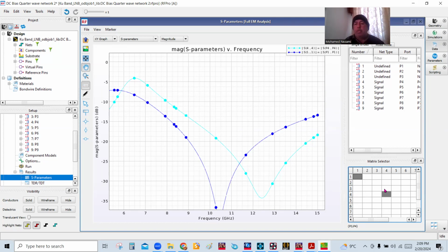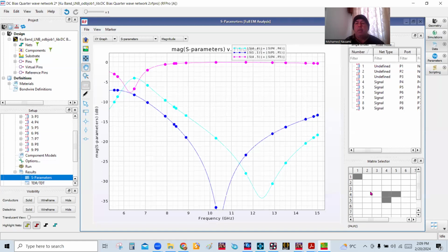And so if you go from 3 to 4, I mean from 1, 2, 3, 4 to 5, you can see that it's minimal loss as well, okay? Where if you go from 1 to 2, it's the same thing. So basically, really, the double stub gives you a much broader bandwidth. But in some cases, and in my case, a single radial stub was good enough, okay?